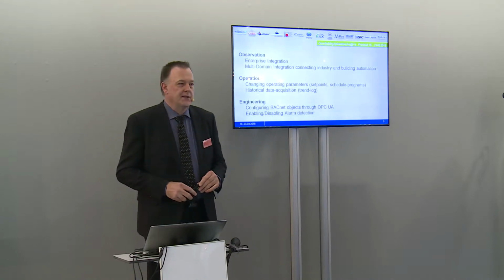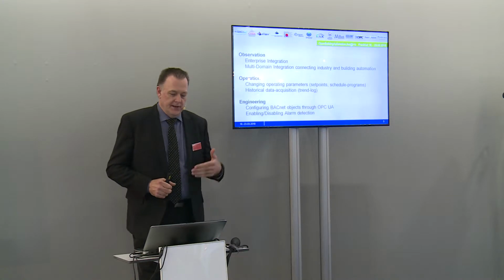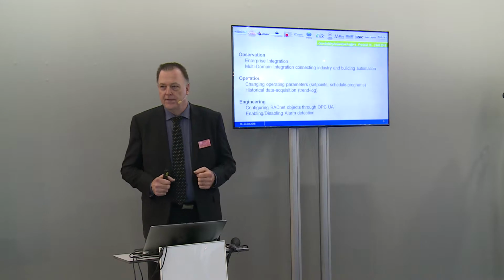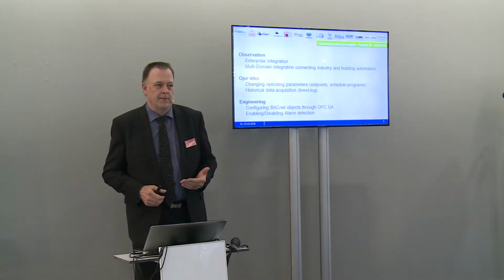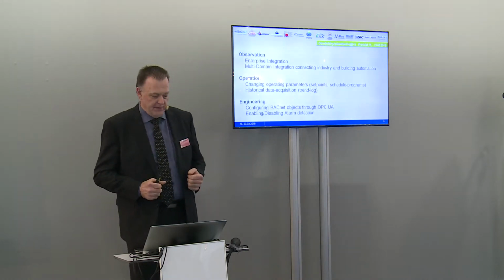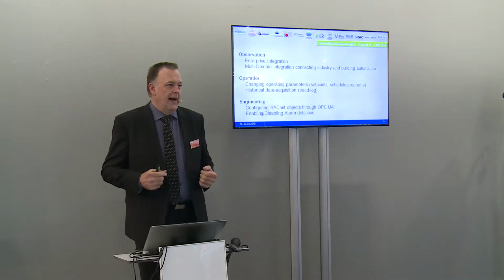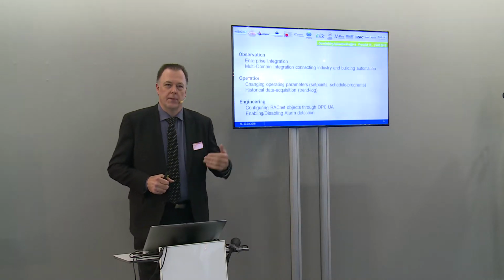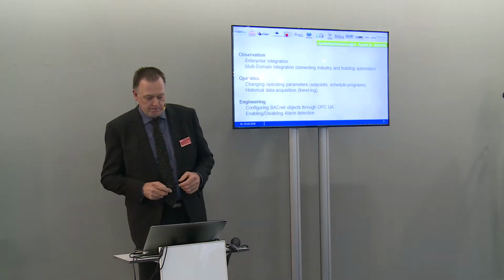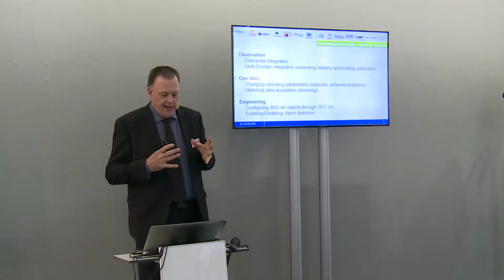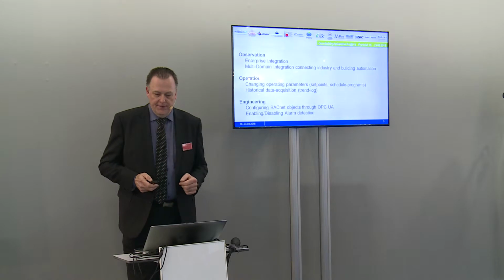When we sat together in the first meetings, we discussed how to model the observation of data from BACnet. We discussed operating the data. That means that a human or machine operator can drive and control the facilities in building automation. That includes things like set points, runtime parameters, but of course also schedule programs, and not to forget trend logging, so analysis becomes a very important point. And of course we also thought about engineering, the high level of connectivity, so that we can not only monitor actual data or drive the parameters, but also do some configuration of BACnet systems from the OPC world. And as said in this presentation, enabling and disabling alarm detection may be an interesting and important point for a facility manager to operate the facilities.